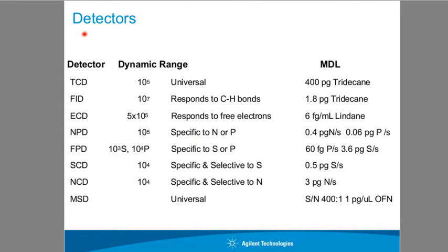Next thing to consider would be our detectors. I put this in here for reference. These are all the various types of detectors. There's probably one or two that are not on this list, but these are the most common ones. I've put on here what they respond to as well as their detection limit. So you can see that TCD is universal, but not very sensitive.